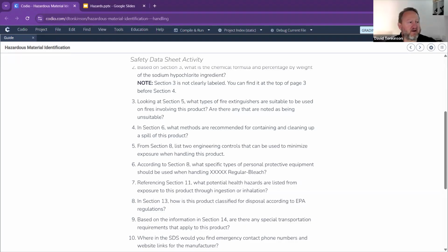So we have safety glasses with side shields. Okay, face shields, rubber or neoprene gloves, protective clothing, long sleeve shirts. Annabelle's cracking it in there as well with the eye and face safety glasses, skin protection with rubber and neoprene, and respiratory. So respiratory equipment as well is basically recommended. The respiratory stuff basically comes in if there is a spill.